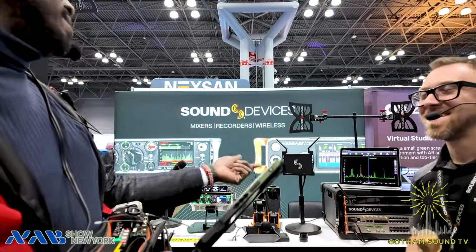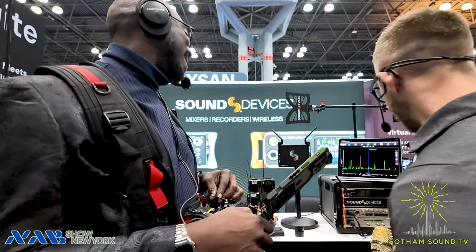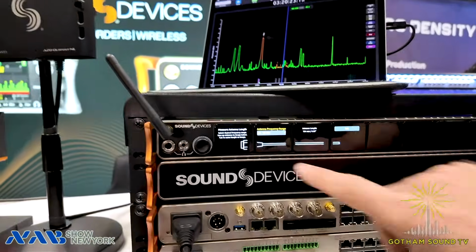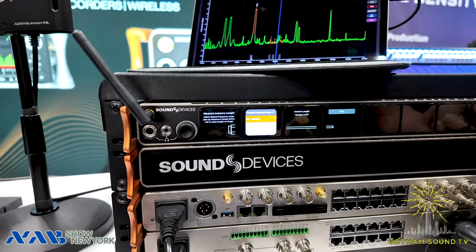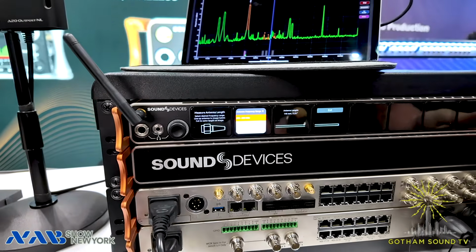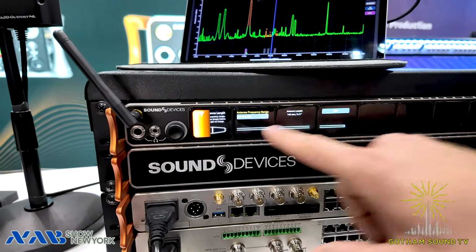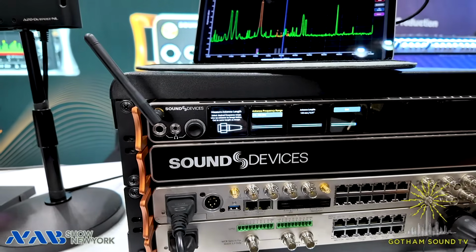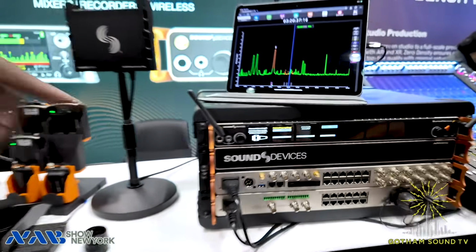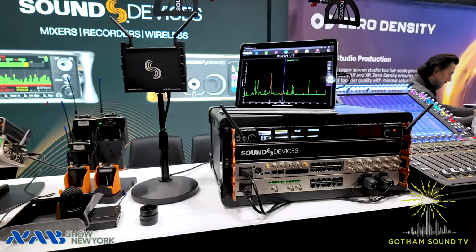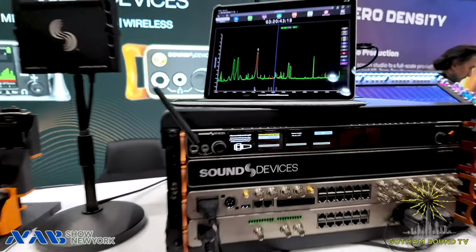I'm curious, can you show me just another size? I just want to see it on the LCD, if you don't mind. Oh, the antenna tool? Yeah. So what we do is we just go in here and we tell it what range we'd like to operate in. There you go. And then let's say 470 to 548. Now it's actually to scale, so we could put an antenna up to this and then know how to cut it, right? And that's all on SMA Con in terms of the visual.